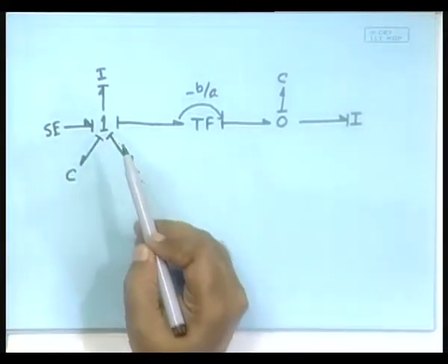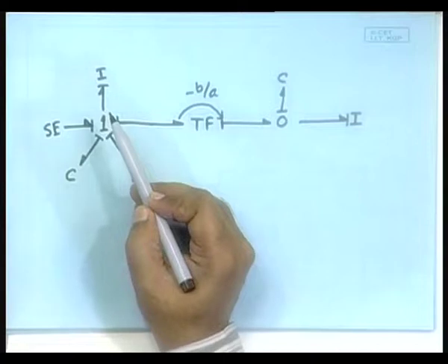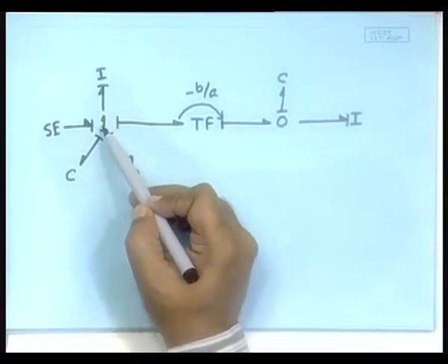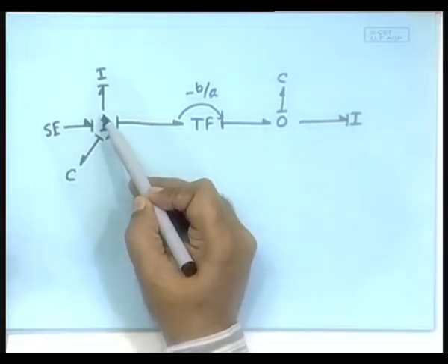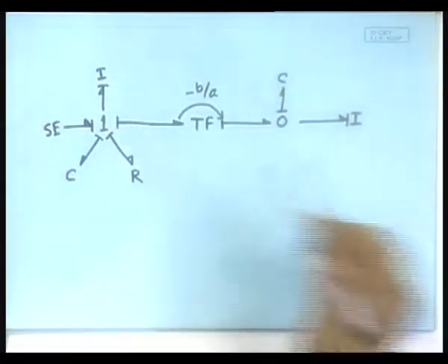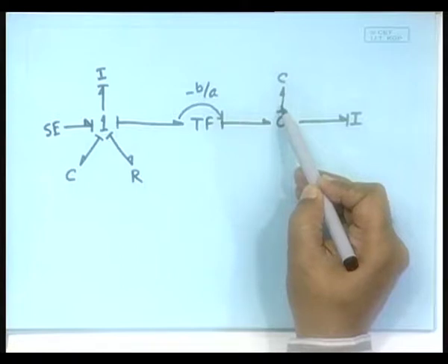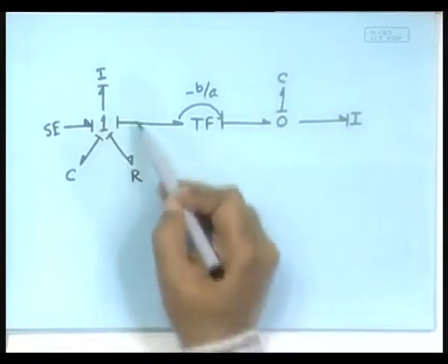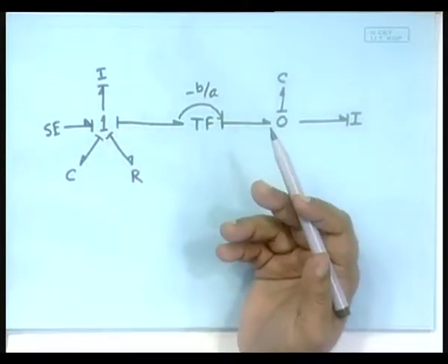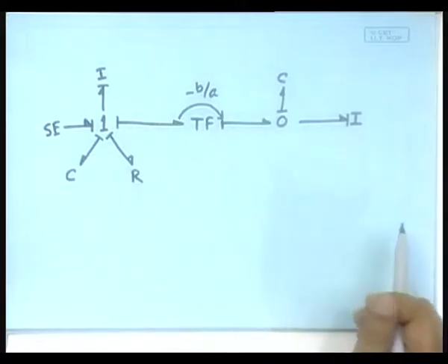The moment one storage element is connected to a strong bond, that means a one junction, if one bond is bringing in the flow information, it is a strong bond. Here is a strong bond. Similarly, here is a strong bond. The moment you have that, the others become automatically determined and you do not have to bother about the rest of the things.